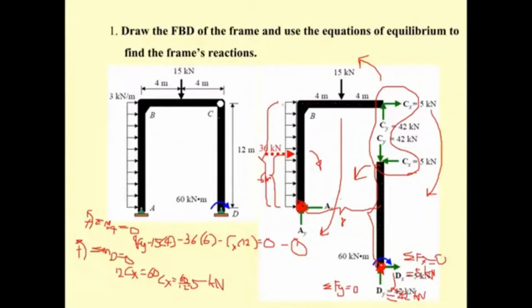And then you come to the frame A, B, C. For the frame A, B, C, in the x direction you may sum f sub x equal to 0. And then you have the c sub x here. You're going to find a sub x, so put this direction of a sub x as positive.